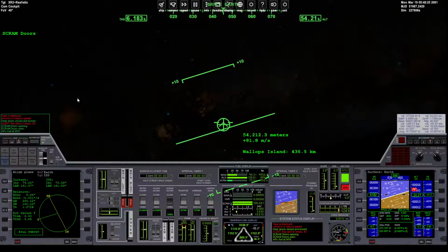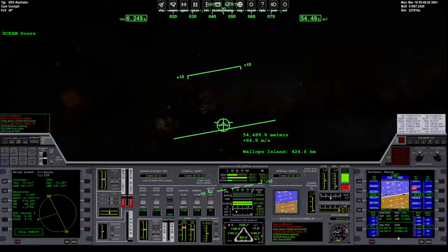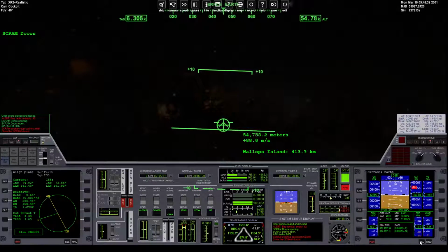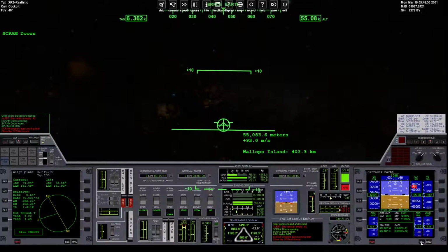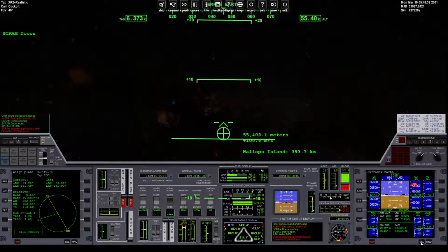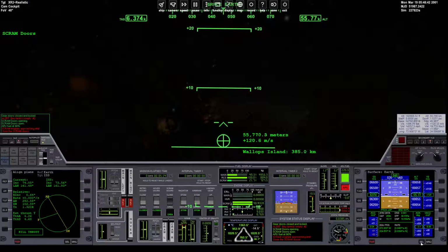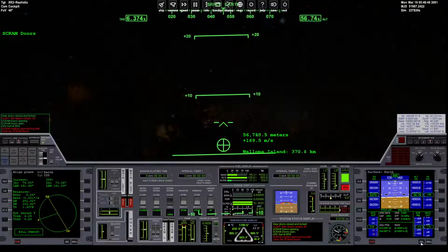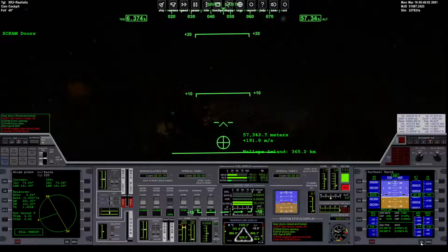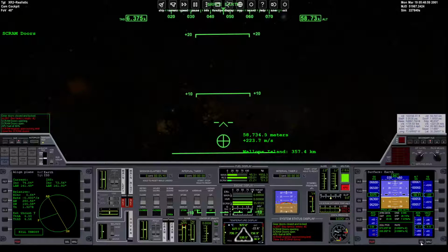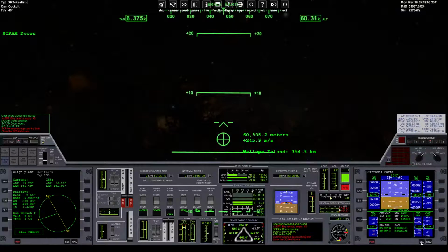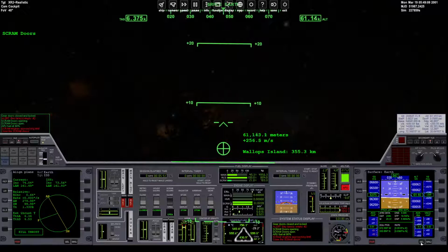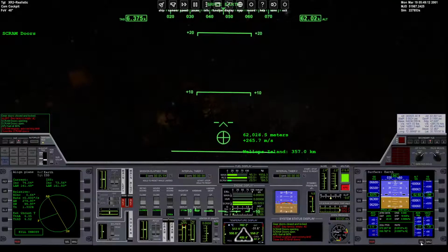But I have found that you can actually keep ascending on those almost at the edge of overheating scrams. Simply climb while... Warning, scram temperature. Right now we're going to begin to climb, because you can see we still have positive acceleration. We're generating some thrust. And this is evident by the fact that our airspeed is pretty much remaining constant even though we're climbing. If we just cut the scrams, that wouldn't be the case still.